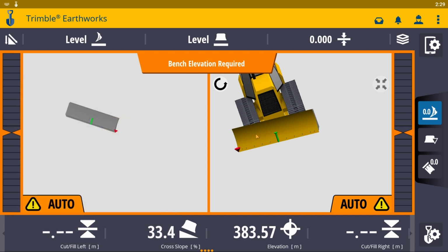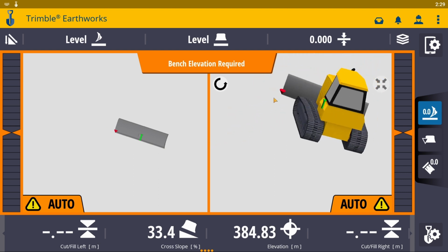Alternatively, you can move the blade up and down to create a whole number here. So say I put it on the left hand side of the blade, and I want my number here to be 385. So this is elevation above mean sea level. So I could lift my blade up here to get me to approximately 385.